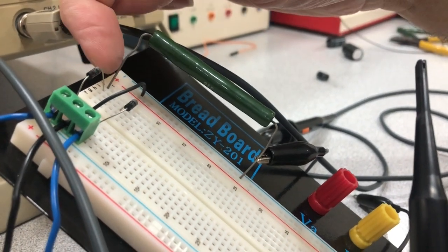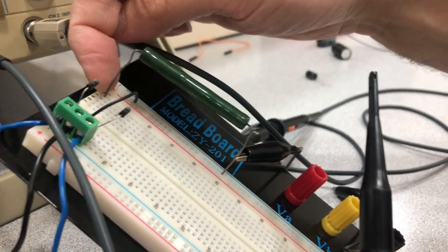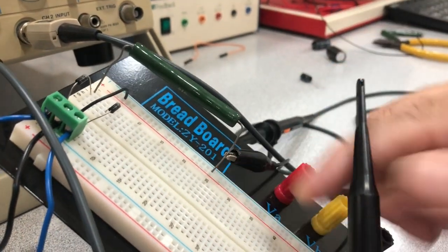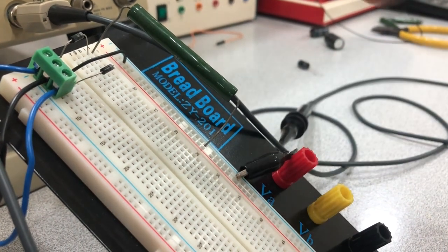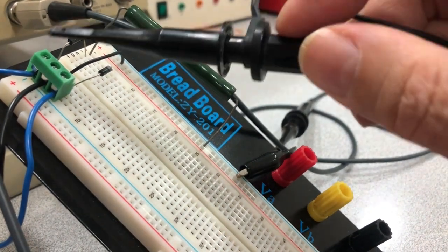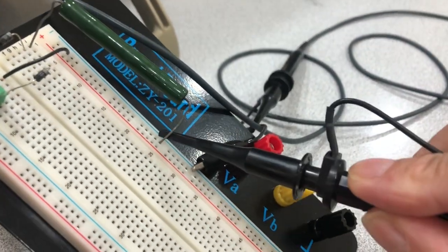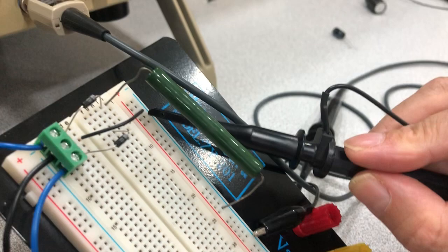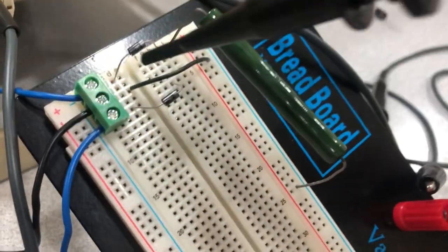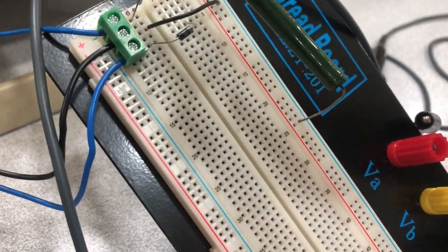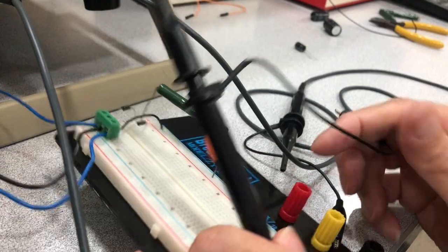Now we took the load resistor and connected it to the cathode, the half wave rectifier output. This entire line here is in common, and we connected it to ground. So now the current is flowing. The positive pulse goes into the anode, out of the cathode, into the resistor, into this blue line. The convention current flows into this black wire and goes back to this center tap black wire in this hole. So I have a half wave rectifier with no filtering. So now the scope has 2 pins.